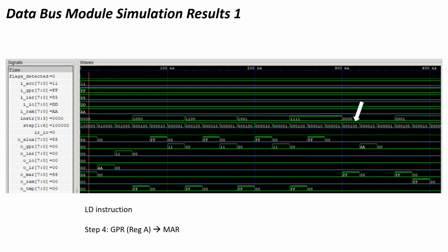They work. So now we go into a load instruction. We go from reg A. This is where we are loading a value from register B into RAM at the address in register A. I know, it sounds confusing, but that's what happens. Register A is the address, and then we enable RAM to go into register B. Step 6, we do nothing.